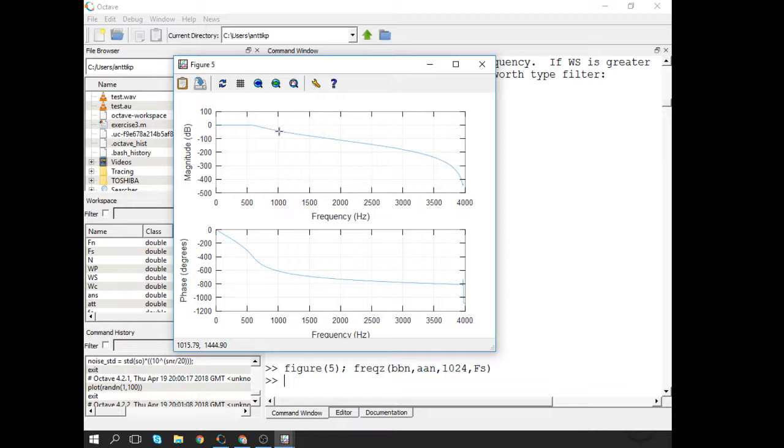So it definitely goes by the default. And by the way, when you're doing the bilinear transformation for these low pass filters, think of the analog filter which has the infinite. When the frequency goes to infinity, then the amplitude response goes to zero. So it always warps like that on these bilinear transformed filters. So that also shows how the frequencies are really warped on these filters.